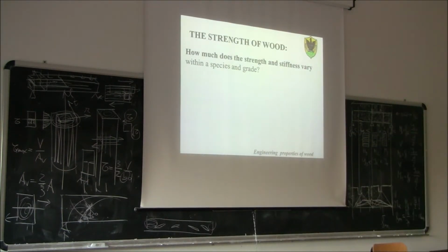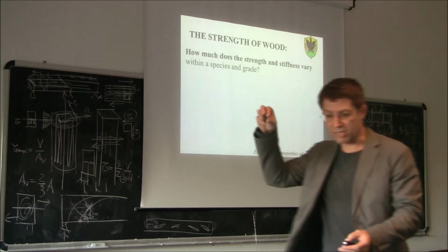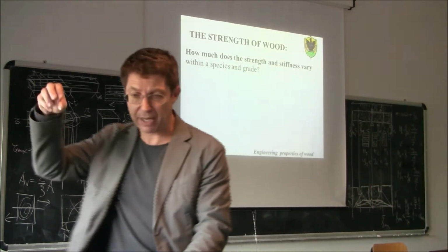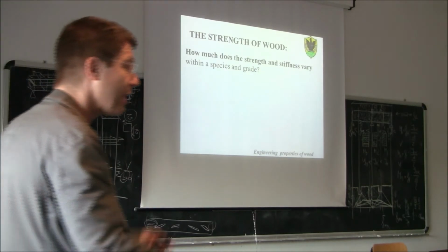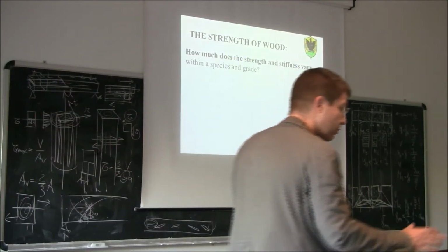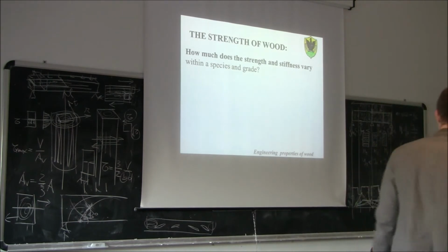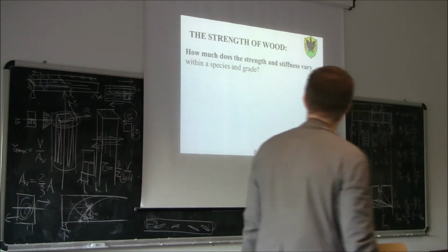And now we want to understand why. Why do we need to classify? Why do we need to spend time and money to grade the timber? Because we will see that timber grading needs some time, needs someone going there to look for defects, measure the defects, or do some non-destructive tests like applying a load and then finding out the modulus of elasticity. So why do we need to lose time and money to do this grading for each piece of timber? This is what we want to understand.